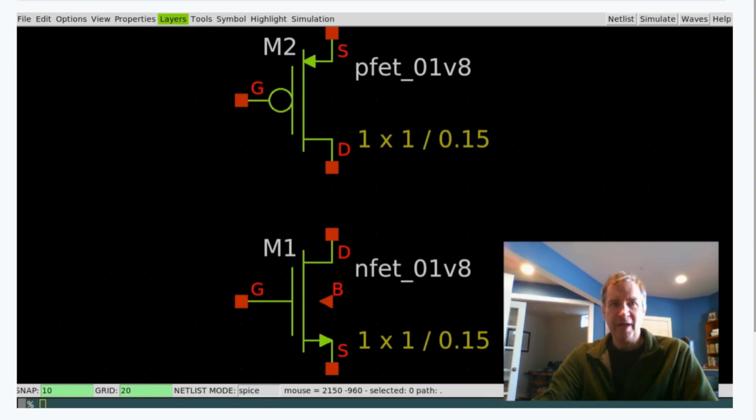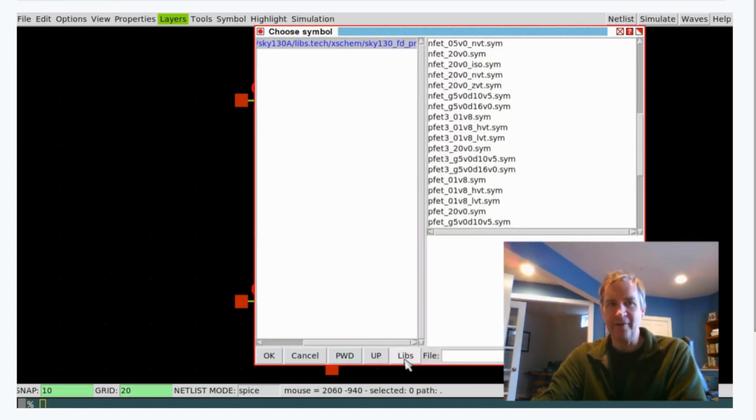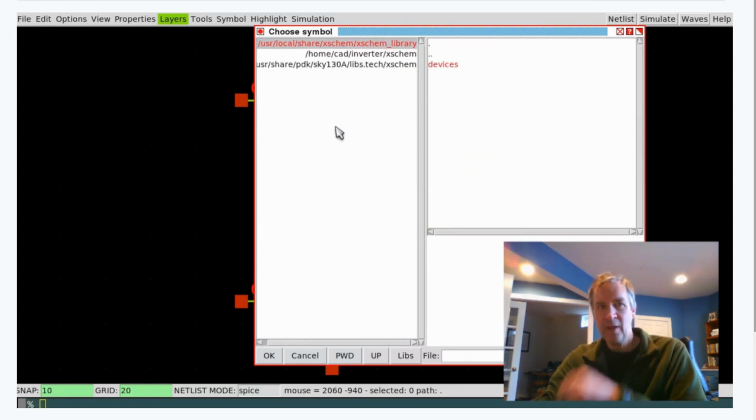Now I want input and output pins. It may be tempting to start putting in voltage sources and so forth here on the same schematic. However, remember that we want to turn the schematic into a layout. The best practice is to keep the circuit part that will be turned into a layout self-contained so that it doesn't have any components in it that wouldn't be part of a layout. The other best practice is not to use any specific power supply pins. It is very convenient to use global names in a schematic, but that doesn't reflect what the layout will be. There is no concept of a global net in a layout, and using them in a schematic can only cause trouble with layout and verifying your circuit later on.